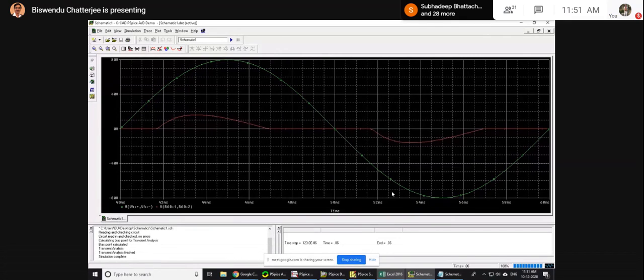my ultimate target will be to measure these true RMS values and powers, as is done in the smart metering system. Actually, if this is the peculiar waveform, then you will see that almost no power will be detected by our classical metering, the rotating disc or the mechanical system. It will be a very erroneous value, and that is the reason we need the smart metering system to be developed, so that consumers cannot escape by producing peculiar waveforms and escaping the electric bill.